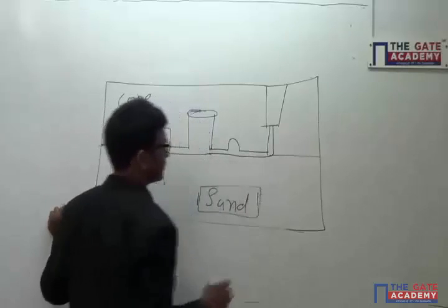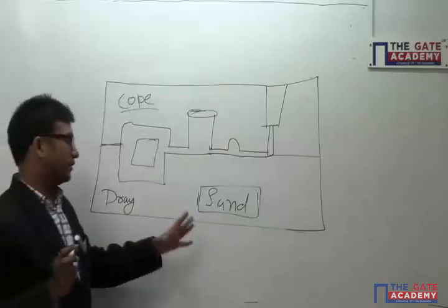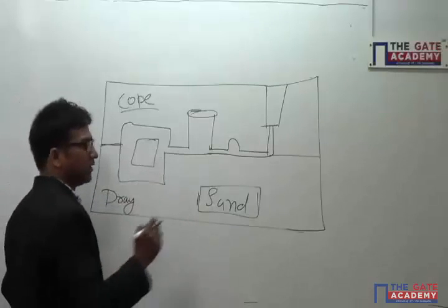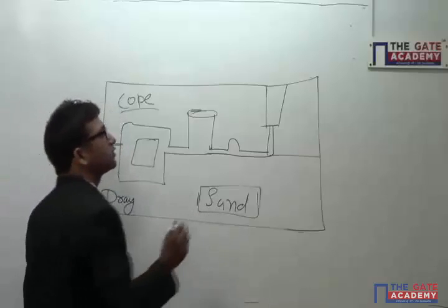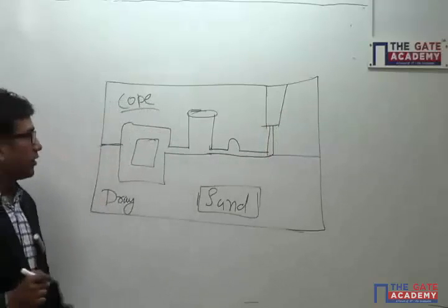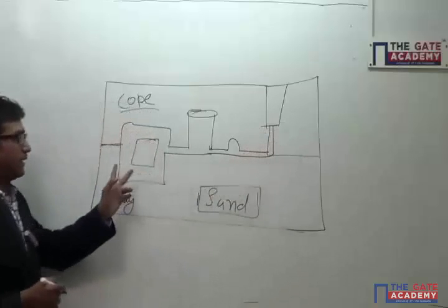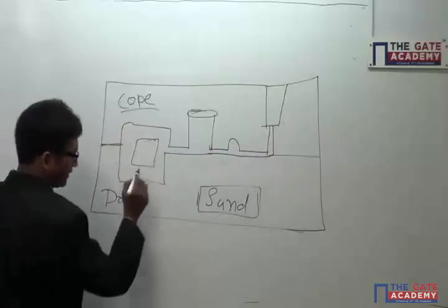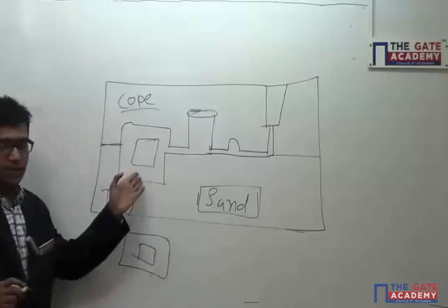In sand casting it is made by sand, or in die casting it is made by some specific material like steel or some carbide material. So most of the time it is sand for the sand casting process. Fine. So we will make a geometry, with some arrangement to flow our molten material to reach this cavity, and my product is the reverse replica of this cavity.